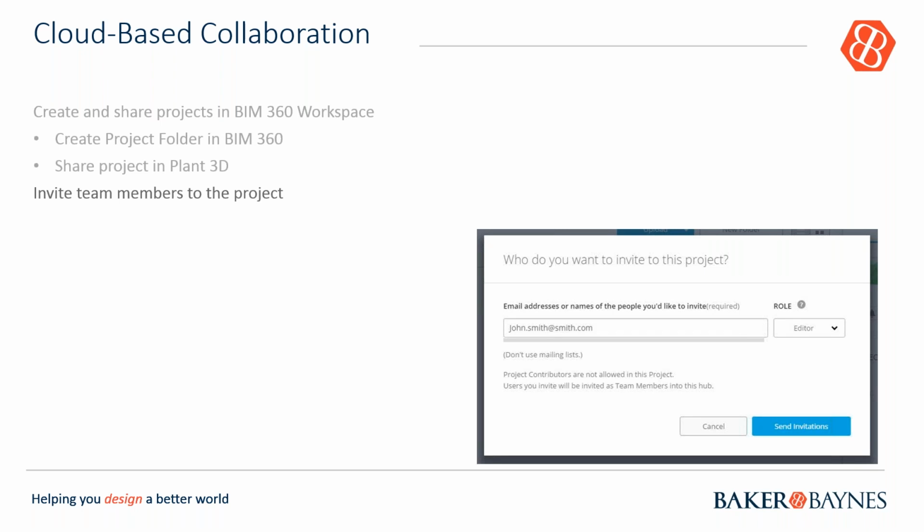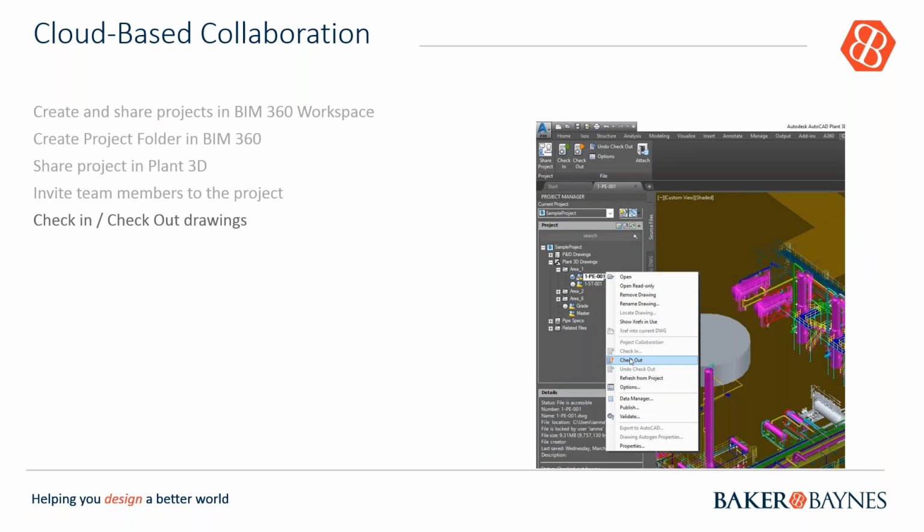And if you're using something like a Vault, or even on the cloud itself, you've got the check-in and check-out of drawings. This is managed by just a right-click and check-out, as you can see on screen. Once a drawing is checked out, no other user can edit that drawing. And of course, users can check the drawing back in once they're finished editing and working with it.